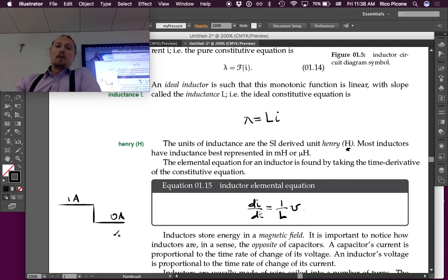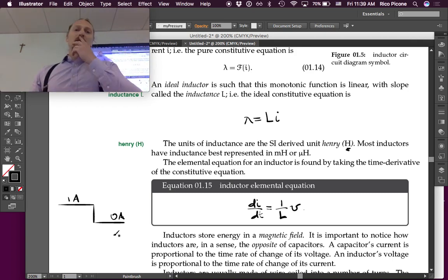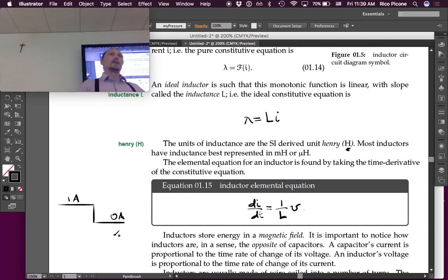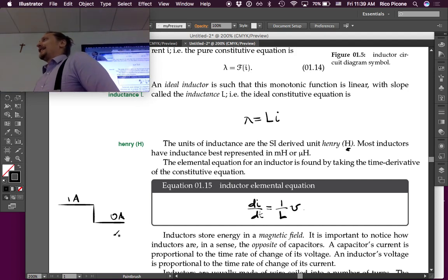So we have to deal with this sort of thing when we have inductive loads that we drive. And there are ways to deal with it, and I'll talk about some of those ways. You can use a component that we haven't learned about yet, which is a diode, but we'll learn about it next week. A diode flows current only in one direction, so we can put a little shunt in and get rid of this difficult problem.